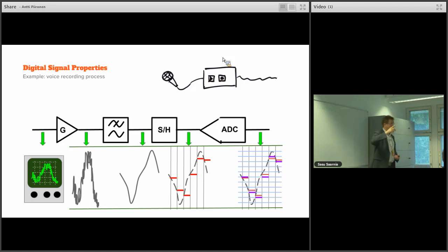You cannot observe with a better resolution than the least significant bit. Which means that the digitized signal is right here, that purple line, which is either a truncation or rounding operation of that sampled signal.